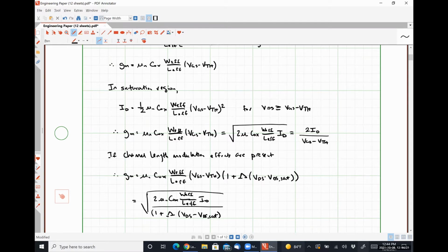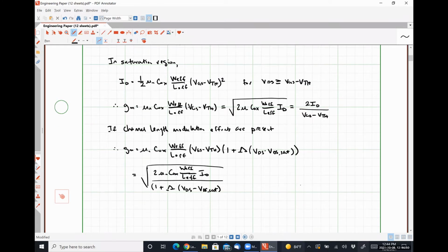Why is that? Channel length modulation only occurs under saturation. For it to occur, we need to be in pinch off and then making the channel shorter. By definition, the triode region does not cause pinch off to happen. So the channel length modulation relationships only occur when we are in saturation. I'm being real clear about that because I've seen people not understand that in the past.